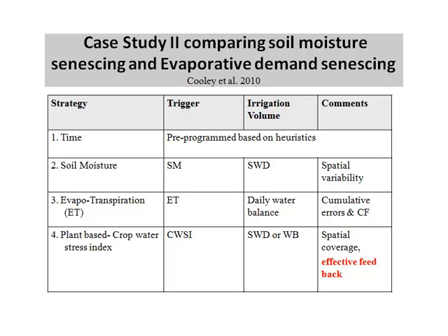A number of strategies were identified. Time, date, which is based on pre-programmed history. Soil moisture depletion. Some comments to make about these treatments. The spatial variability of soil moisture is something that needs to be considered. This is overcome in evaporative transpiration, which is based on climate.